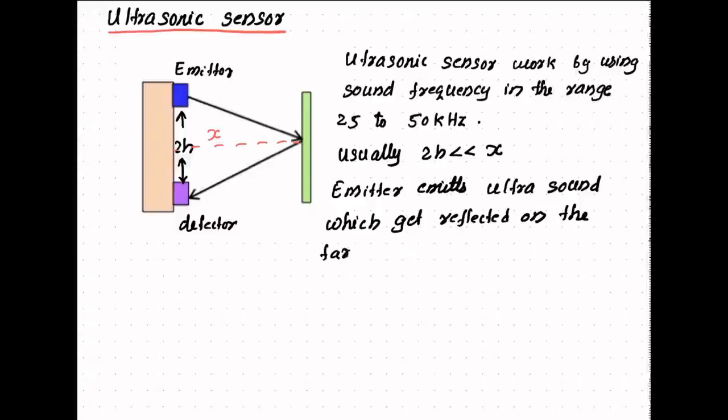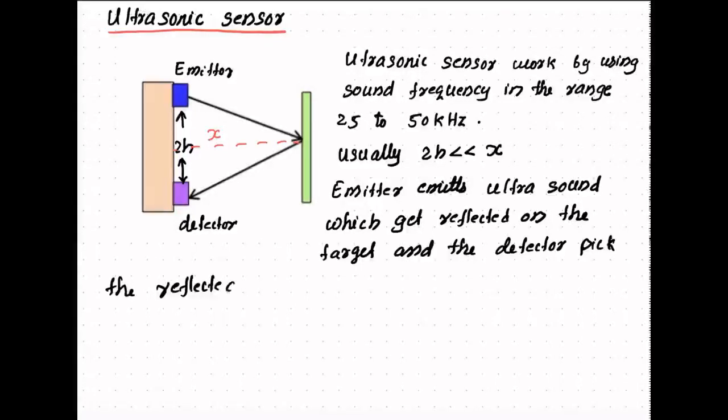Now in the ultrasound sensor, we can measure the time taken for the sound to travel from emitter to target and come back to the detector. We know that time value and the speed of the sound wave, so we can easily calculate the distance between the target and the ultrasonic sensor.